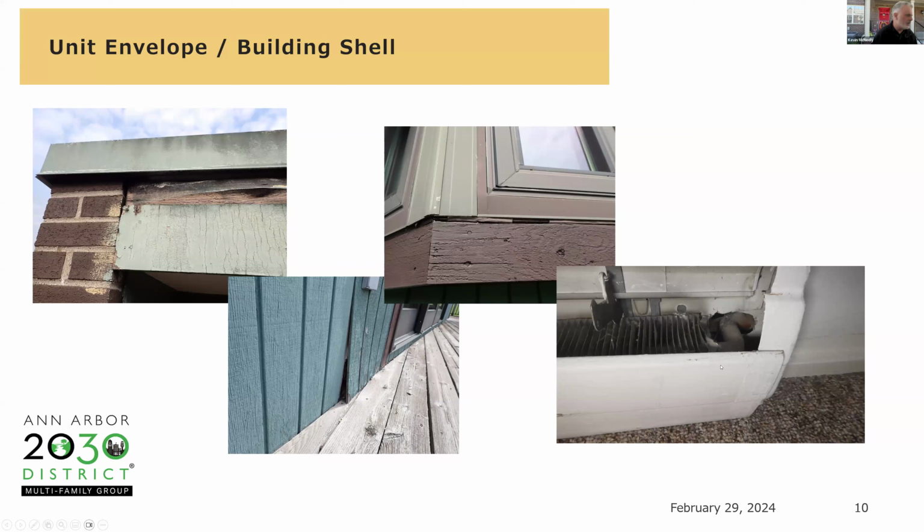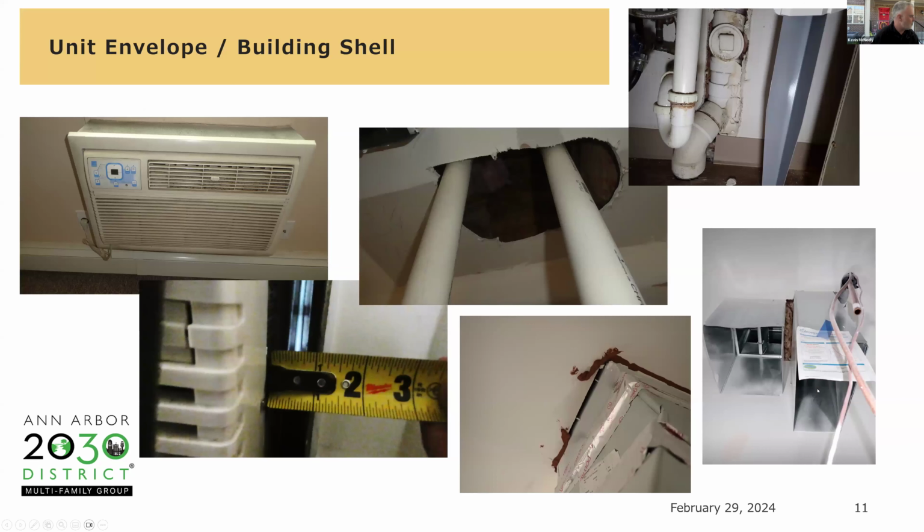In a lot of older buildings, we have baseboard radiant heat, and this is hydronic. So this is kind of to the right-hand side of the picture here. We have the hot water line coming into the radiator. So again, that could be filled with fire stop caulk. Make sure it can handle the heat that's coming through that pipe right there.